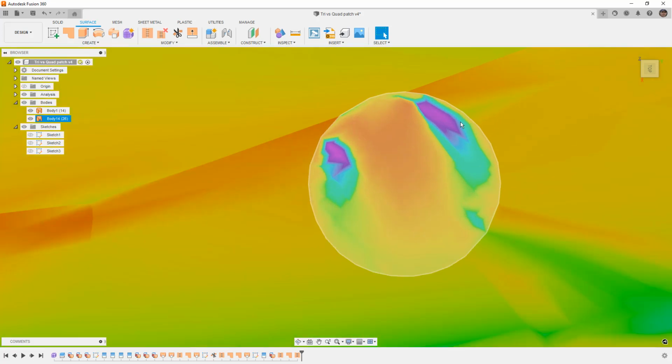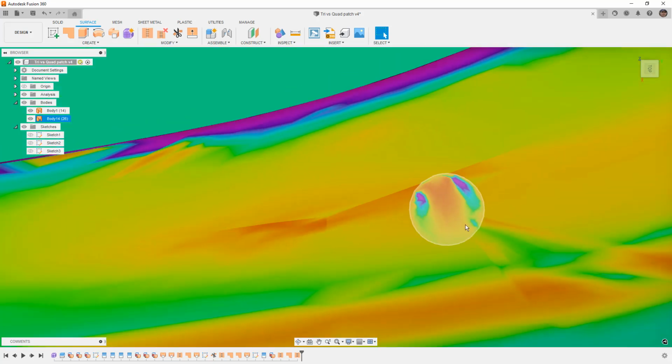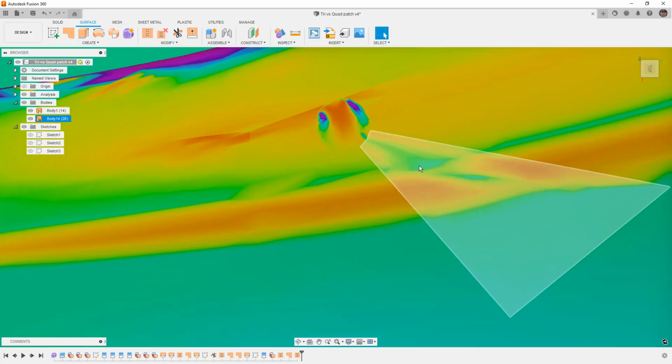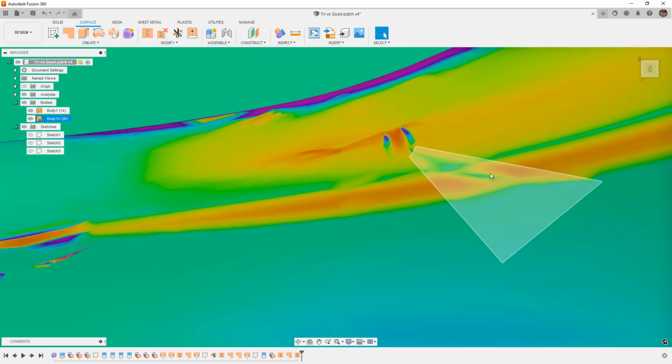And that's again because when we use the patch tool, it gives sort of equal opportunity to every section of that edge. So that means this little green section here, potentially the yellow section, the red section, this green section, they were all influencing the curvature in that small area. We can also see that we do have this sort of disjoint that happens in that edge.